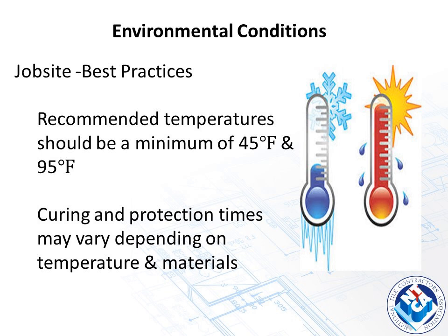And again, the curing and protection times may vary depending on temperatures and the materials. If you've got an exterior cladding, for that matter, and the temperatures drop after installation, it's going to take a little bit longer to cure. If it gets too hot, they may go off too fast. In the case of a mortar bed on a wall, you're probably going to want to wet that down a few times before you start installing tile on it. So really, the temperatures can make a substantial difference, and keep that in mind during your installation.